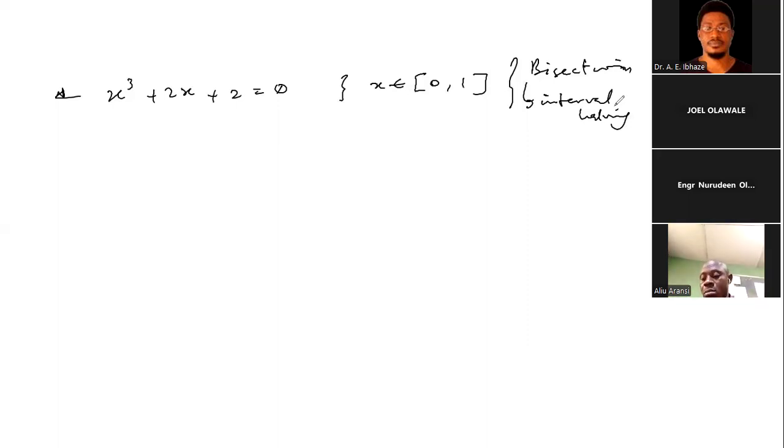If you go into evaluating the poles of that characteristic equation, or the roots, which we can now say are the poles, then you can also tell if the system is observable, if it is controllable, and the like. So everything that has to do with characterizing the performance and the behavior of the system falls within these roots.